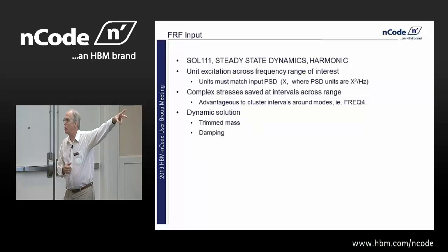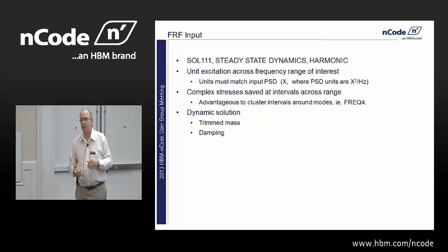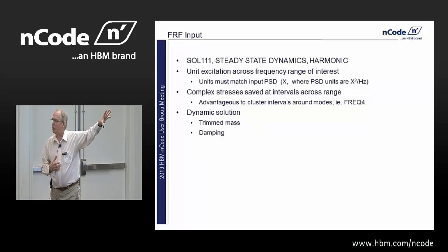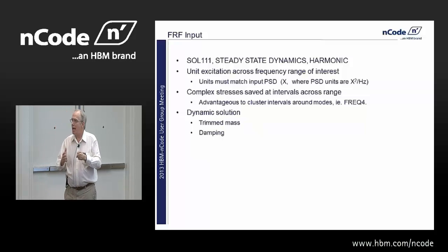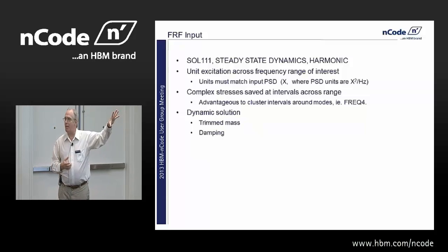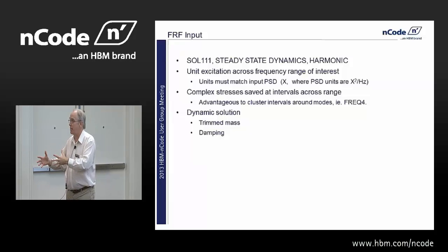So the solution you're going to be doing is some sort of harmonic analysis. No matter what analysis code you're using, you're going to put a unit sweep across the frequency range. This unit load could be acceleration, force, or displacement. One thing we have to worry about is units in general. We want the units of this harmonic to match the units of the PSD.